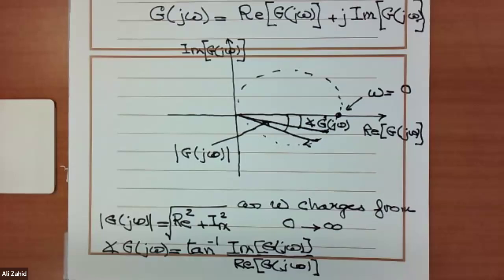In exactly the same way as root locus was able to tell us whether the root locus will intercept the j omega axis, so that we make sure that K, which is the gain, does not exceed that value. Otherwise, the roots will go to the right-hand side of the s plane. Did you get it?